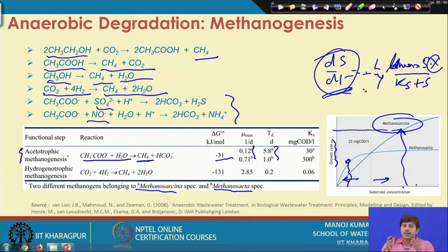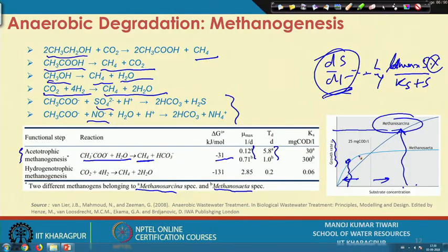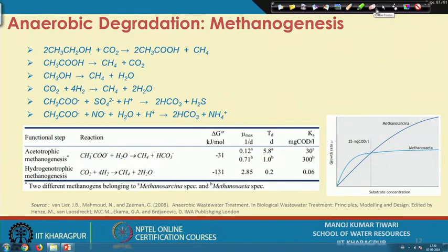But if we are working with relatively lower COD and want to bring it down further, because if your effluent COD is decreased, if you are working in this range, then if you are working with Methanosarcina, Methanosarcina here will not be able to show adequate growth. Methanosarcina here will have a lesser growth rate as opposed to Methanosaeta.